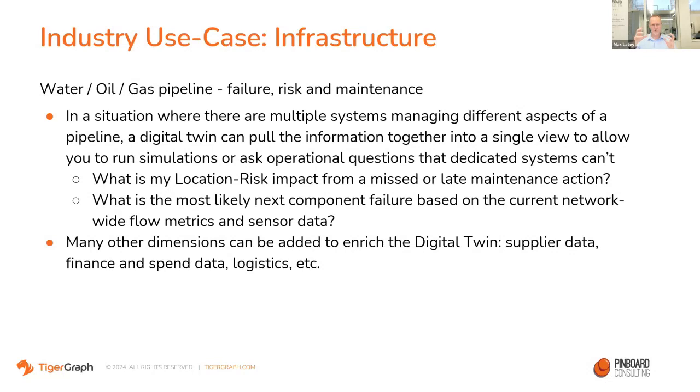These are networks that are incredibly amenable to analysis in a digital twin. And what we're finding is that there's a lot of standalone software that already has some notion of a digital twin without calling it that. You may have software which manages your sensor network, another which manages pressure, another which looks for leaks or strange flows. If things are supposed to flow one way in a pipe and a sensor says it is flowing backwards, you probably have a leak somewhere further up the line. They already exist.